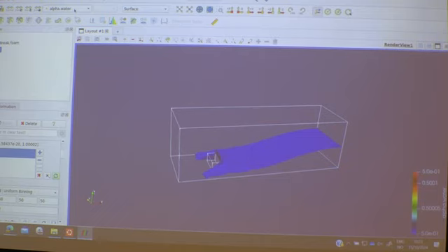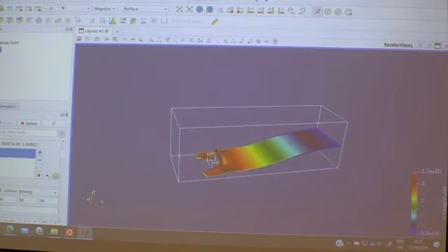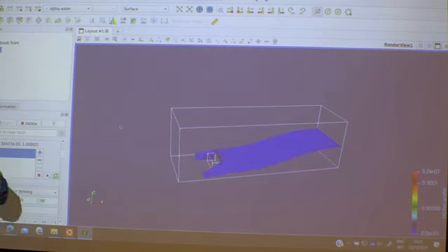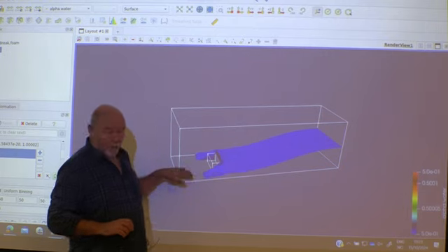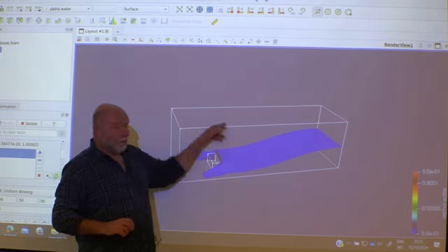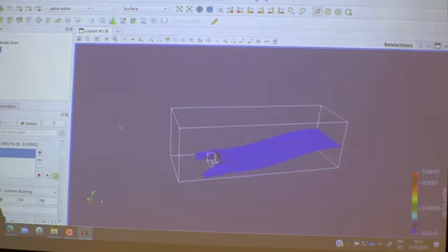The air is also moving, so it's not only the water lying in the bottom of the tank, the air is also moving here, and hence also produces a pressure. Not big, but it's going to be there. So you have some small values, but then when the water hits, of course, you have a density difference of 1,000, so that's completely different pressure.